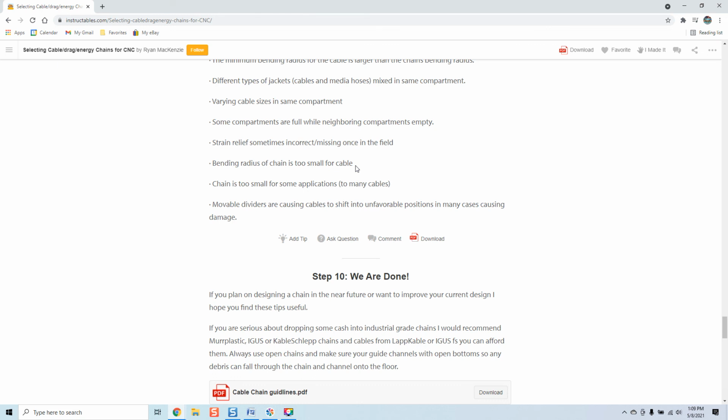I'm trying to think of them. There's so many of them. Shapioco is one of them, I know that, and there's a couple others that are like that. But those are notorious because the chain is usually too small. It makes a very, very, very tight arc, and what the end user does is he'll use that chain mounted on the chassis, keep the arc as tight as possible, and then it can usually cause all kinds of problems, especially when the cable chain is overfilled.